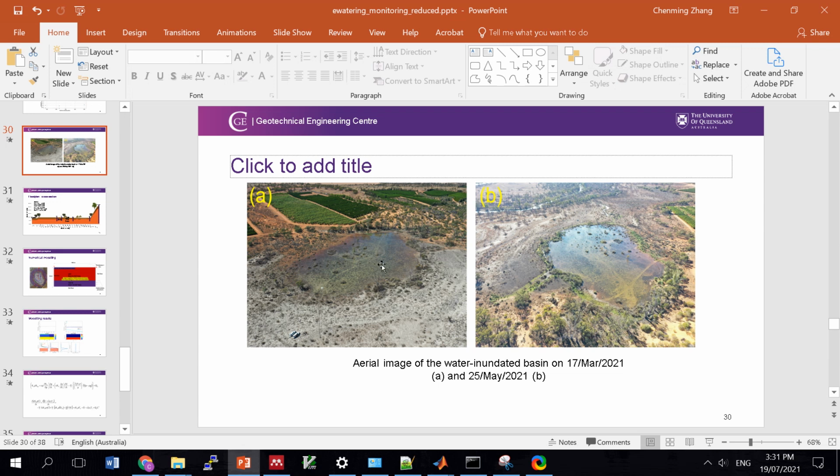And what we find is that the water table is about 5 meters below the surface, and that is being bulged, increased. So the water table under the pond is increased, but the ambient environment is still the original water table. And that means the groundwater will dissipate as it goes away from the pond and eventually become a flattened water table.